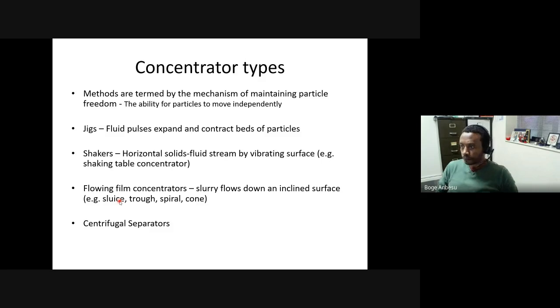So as I was saying, in gravity separators, density is obviously the main property, but particle size is also another factor that may affect the performance of a separator. And therefore, all we do in designing these gravity separators is somehow manipulate how particles move inside the separator.